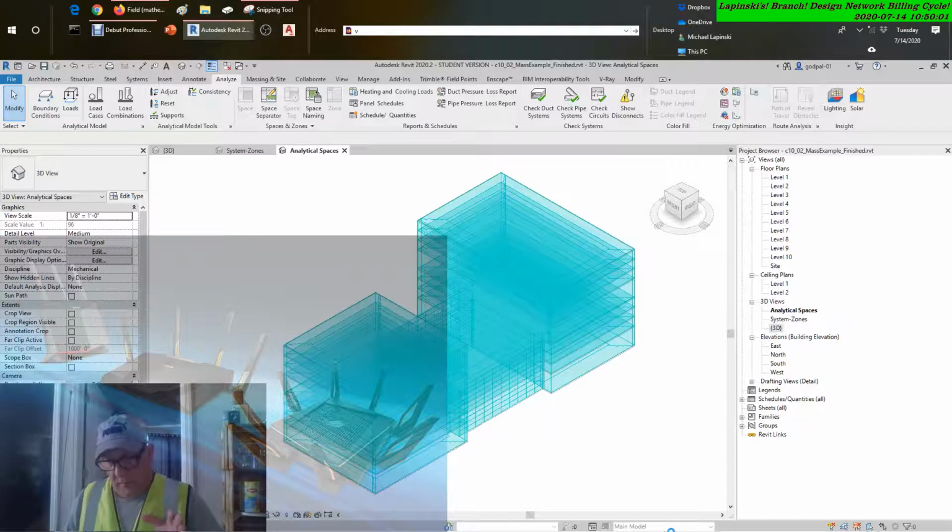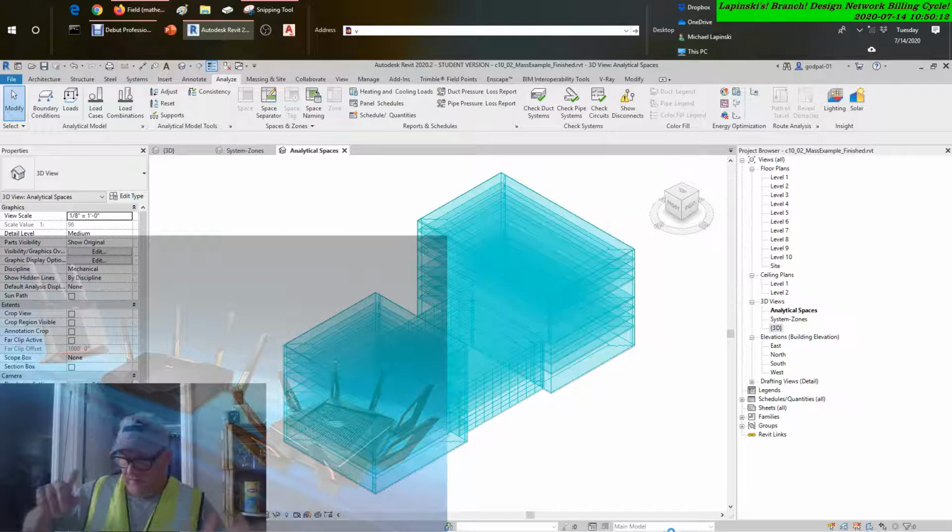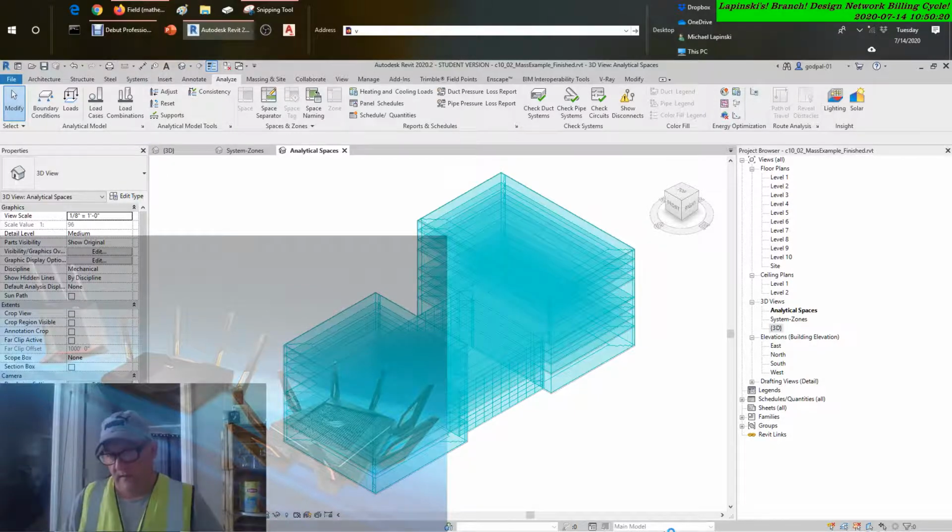Choose Insights from the menu along the top of the dialog box. This will take you to the main Insight 360 screen and allow you to create a project. Click the plus create insight button, select the model you just ran from the web, and click done. This will effectively put that model run into a folder within Insight 360.